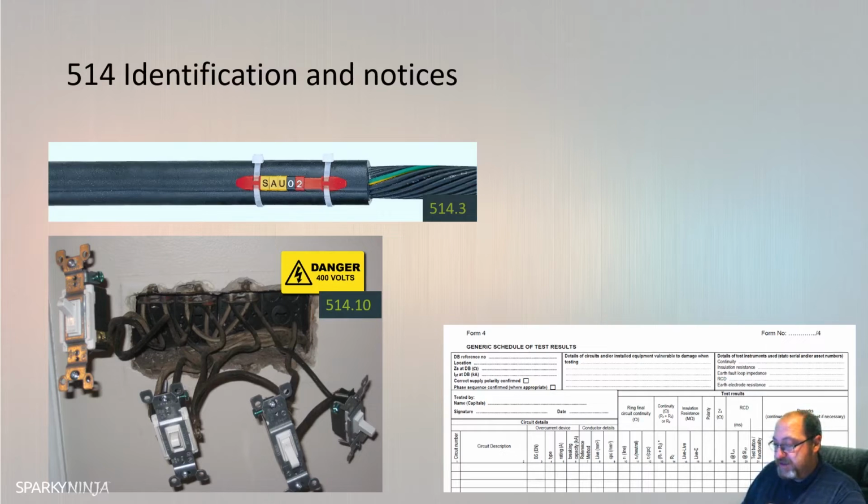The protective conductor. The bicolour combination of green and yellow will be used exclusively for the identification of a protective conductor. This combination shall not be used for any other purpose, and with this combination, one of the colours will cover at least 30% and at most 70% of the surface to be coloured. So when you come to the yellow and green, you need to have no more than 70% of that being one colour and no less than 30% being the other.